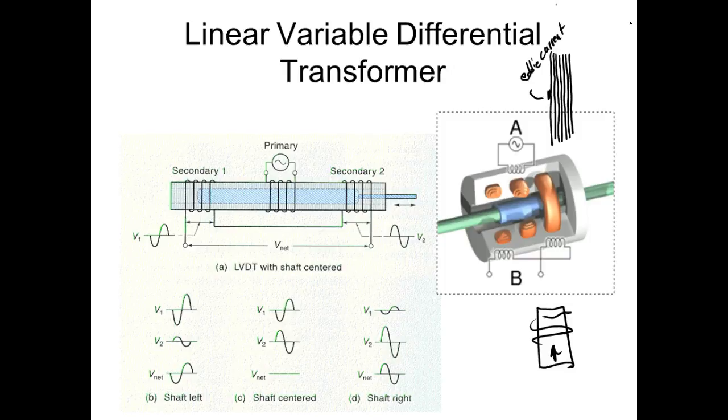So you can see a motor, I think I got a picture somewhere, a motor that's gotten way too hot, the lamination will turn black, and you've got a big problem after that. It's basically charred the lamination, and now you've got windings that are shorted, and that's going to cause a big problem. So yeah, they're isolated from each other. This shows it as being orange. It kind of looks like copper, but it's not. They're all laminated.